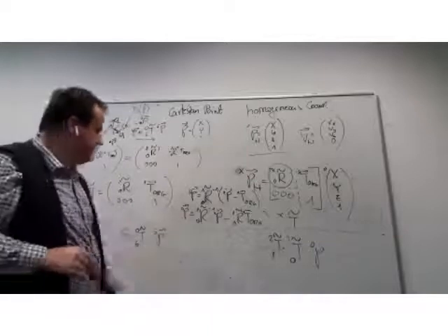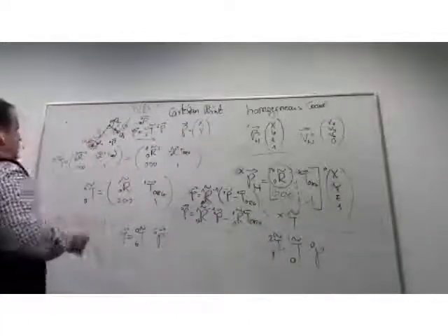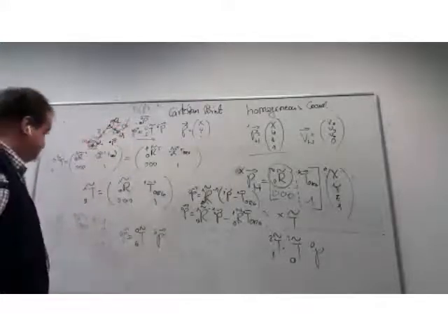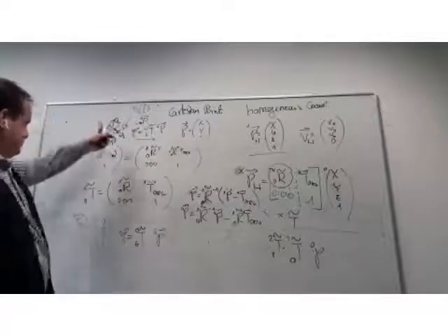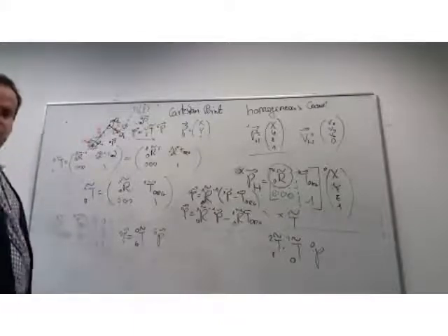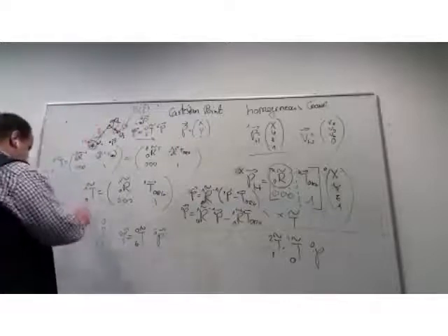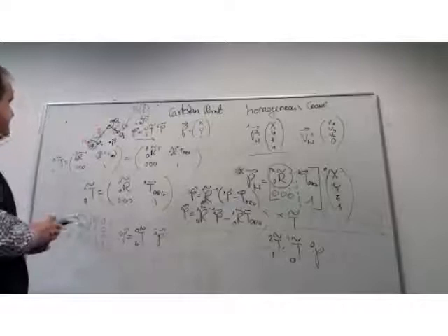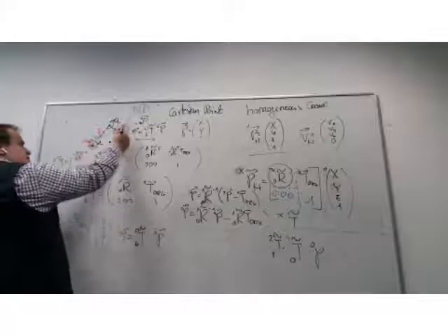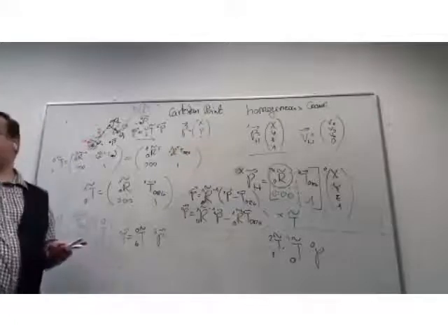So if I apply the sequence of transformations, I calculate in the end a vector which connects the base to the wrist. And I have 0, 0, 0, 1. What did I gain? Well, this thing is just the position of the wrist in the base plane. So this is exactly my forward kinematics.